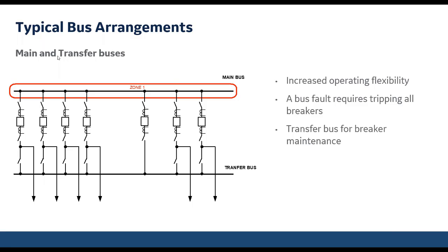So it gives me tremendous flexibility for maintenance. And if I have a fault on the bus, even though I'll trip the bus, I'll lose my loads temporarily, I can always transfer over to the transfer bus and pick up my loads fairly quickly.